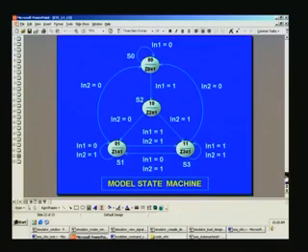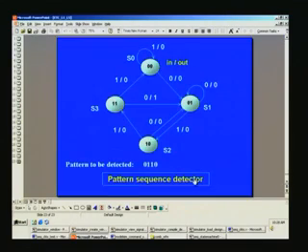Next one we will consider is the pattern sequence detector. In this detector we once again have 4 states, with this as input and the corresponding output. We need to detect the pattern 0110. We will start with this, and if the input is 0, it will go to this state. Because it is 0 in this state, we then go through as per this. So, we will once again go through the waveforms for this.